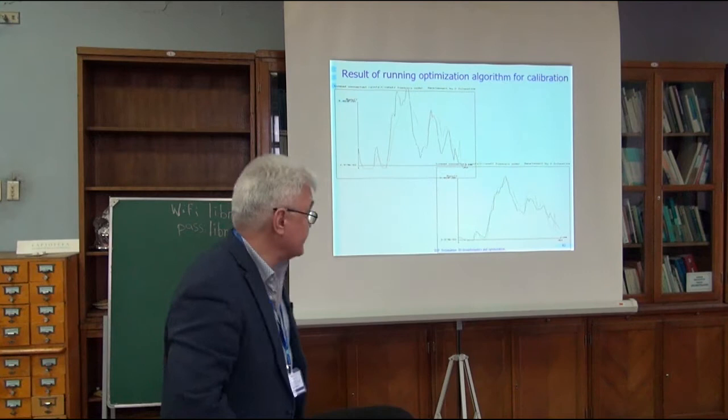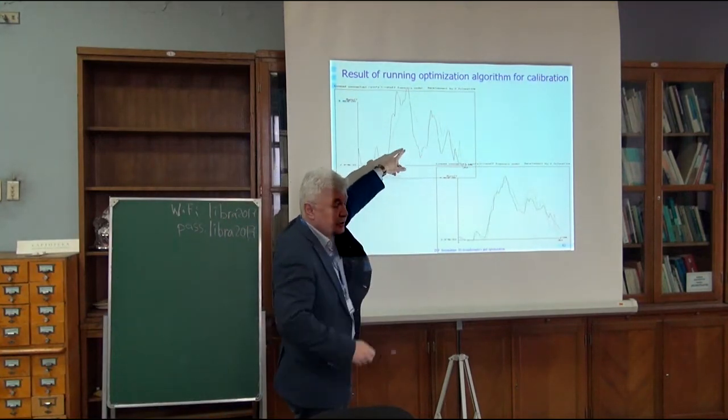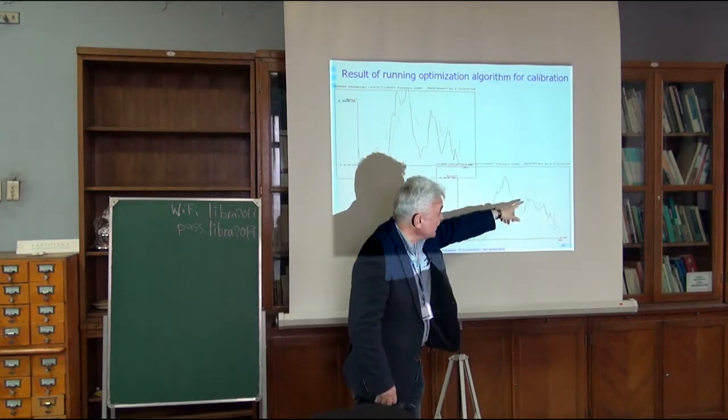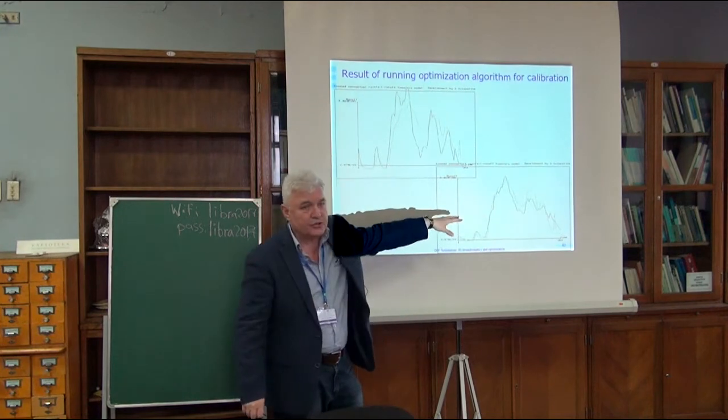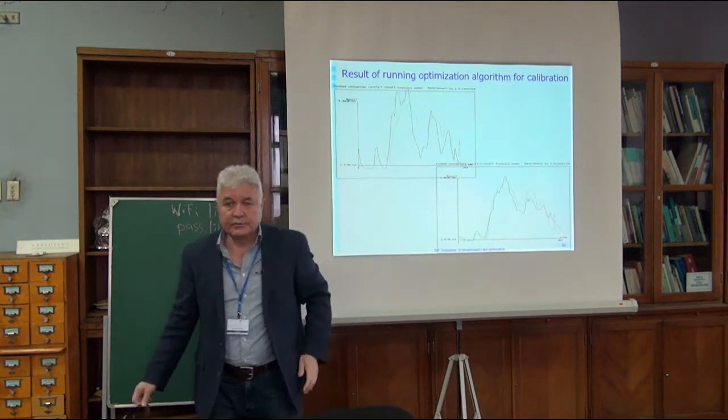Yes, and this figure actually shows a model run before calibration. You see the hydrographs are quite far from each other. And after calibration, you see you have a much better match between the 2 hydrographs, observed and modeled. Okay, so it's a result of calibration.